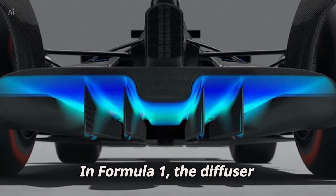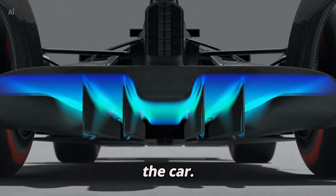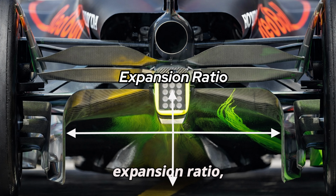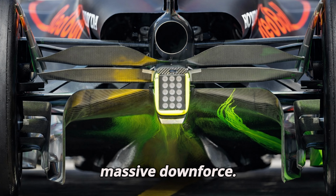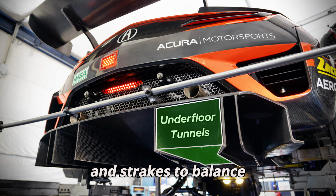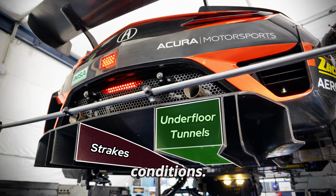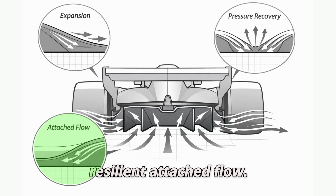In Formula One, the diffuser is often cited as the single biggest downforce-producing device on the car. Its geometry is tightly regulated, but teams optimize its expansion ratio, strake placement, and interaction with floor flow to eke out massive downforce. In GT3 and endurance racing, diffusers are shaped and integrated with underfloor tunnels and strakes to balance stability and efficiency over a wider range of conditions. In all cases, the same principles apply: controlled expansion, pressure recovery, and resilient attached flow.